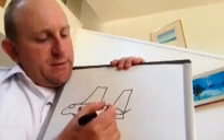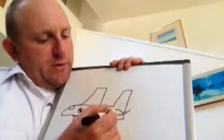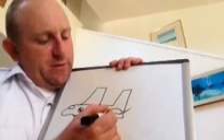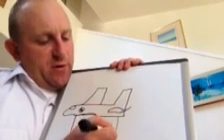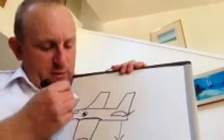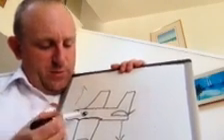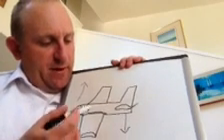And what that does is it reduces our camber, it reduces our lift, and what will happen is the tail of the aircraft will go down and the nose of the aircraft will go up because we're rotating about the center of gravity of the aircraft.